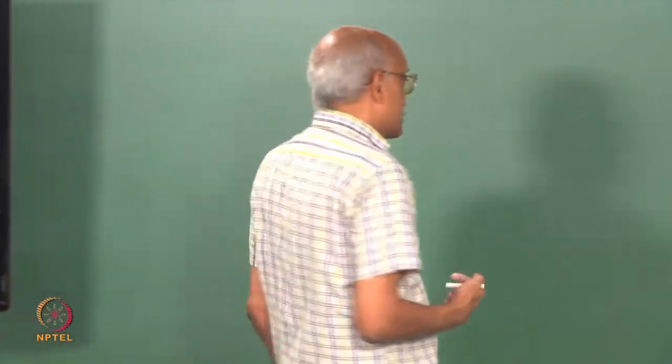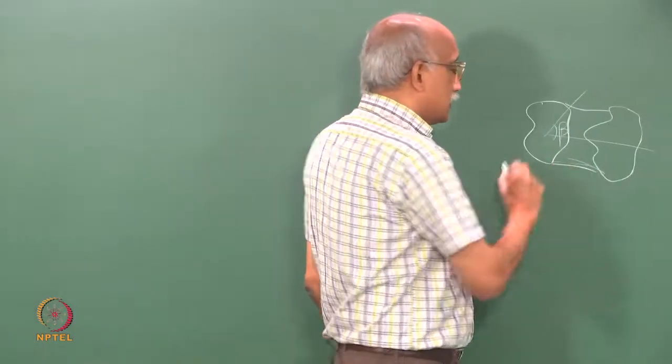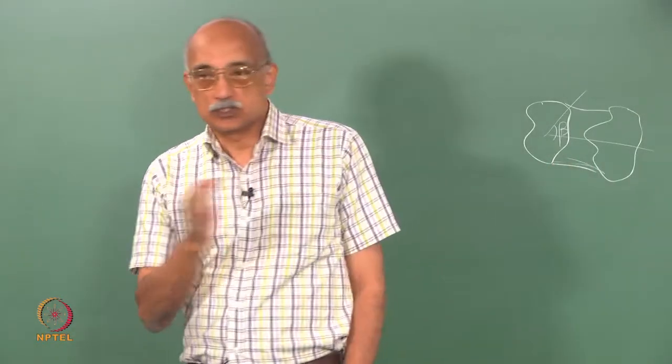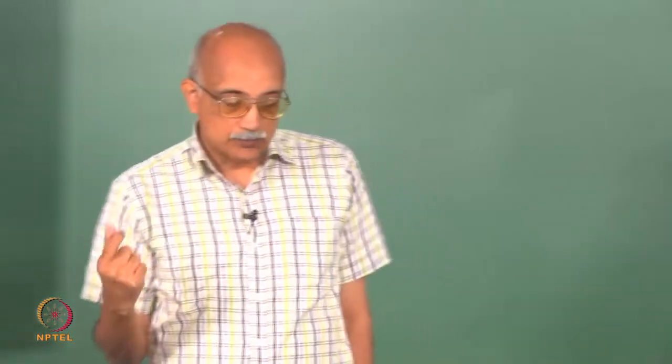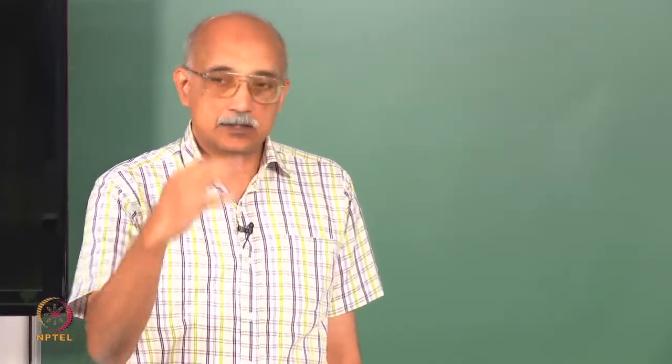Surface tension forces happen because of the formation of a meniscus between the two particles. The pressure forces happen because there is a pressure differential at the interface between the particles and the gas or fluid in which they are suspended.